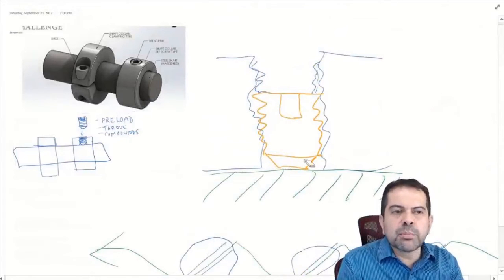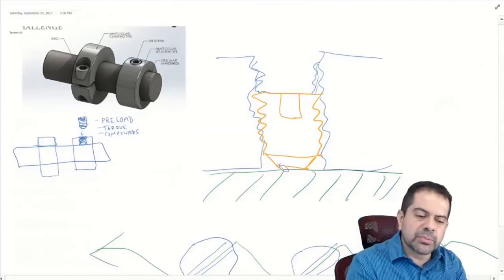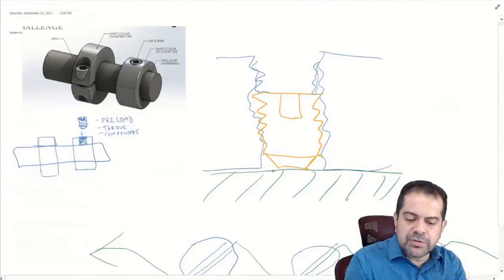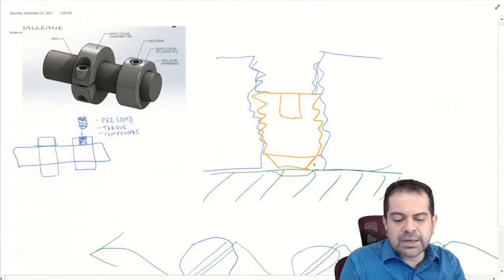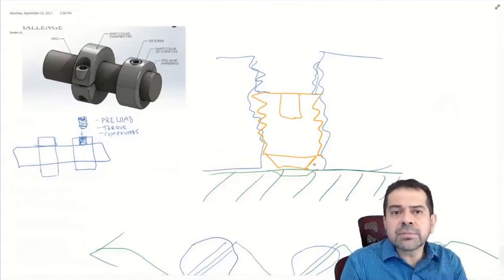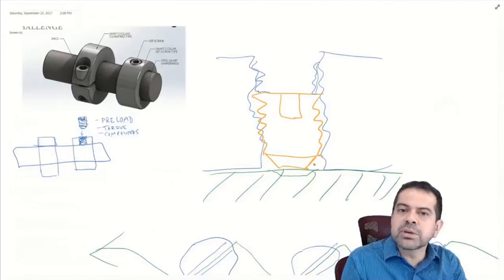There's something called marring. Marring is deforming or damaging a surface. So the more we tighten this, we're probably going to start to deform or indent the surface. There are times when that does not matter, and if it doesn't matter, you go with that. But there are times when it is a problem. Let's say this is a removable component.